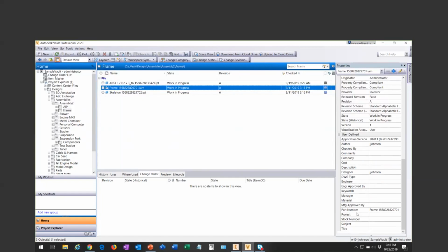And again, why that might be important is that having your properties exposed in the panel here gives you a little bit faster access if you're going to modify them. So you can just come in and click on the value, and up here in the upper right-hand corner, you can have edit properties, or the easier one is edit selected properties.